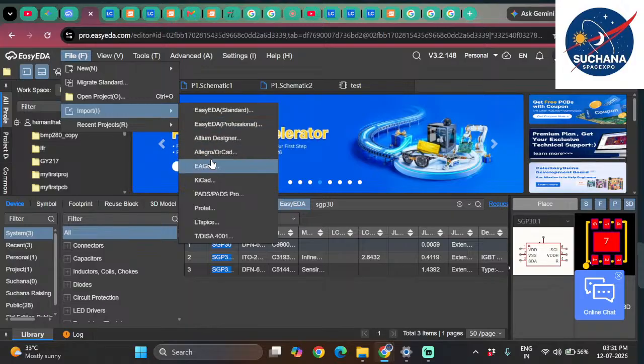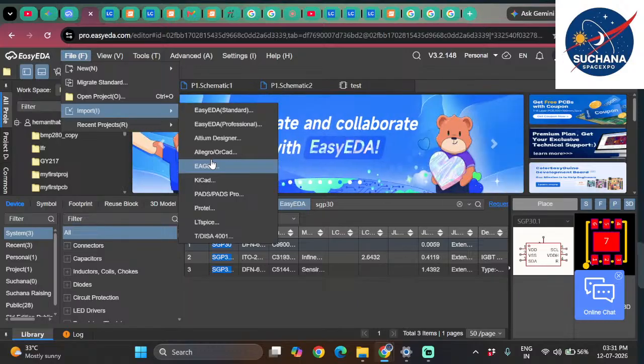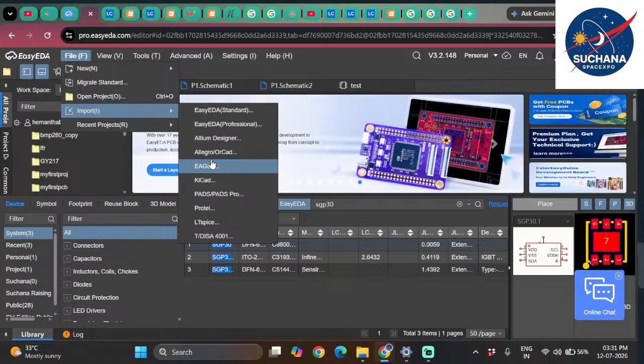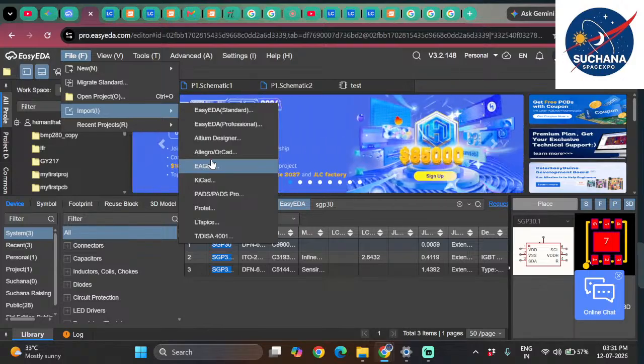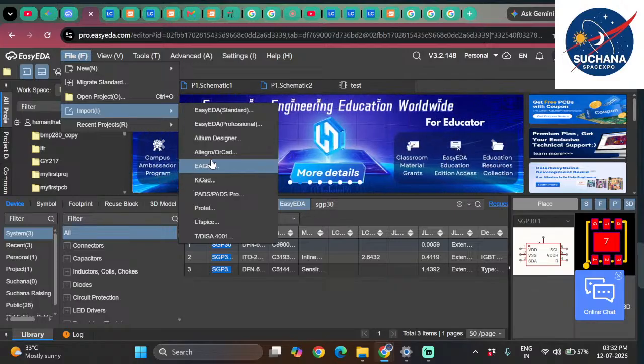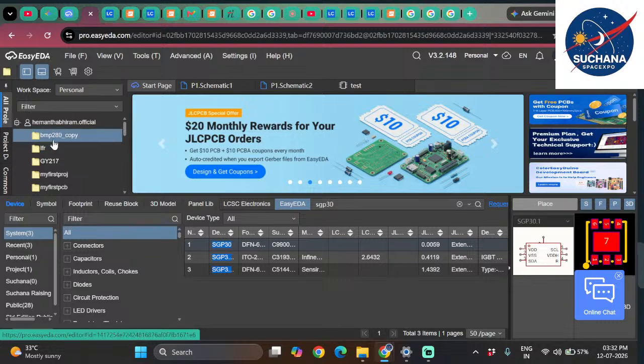But there are drawbacks. Components imported from other PCB vendors have a high probability of undergoing mutation. They are not always rendered exactly as exported from the original vendor, so there would be a little mutation. That's why I suggest you go with either Altium Designer or KiCad. Both are highly professional standard.